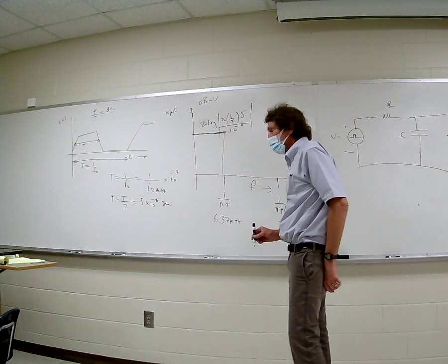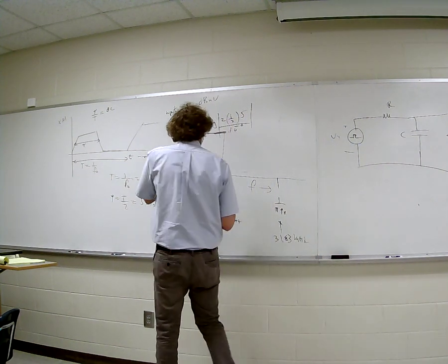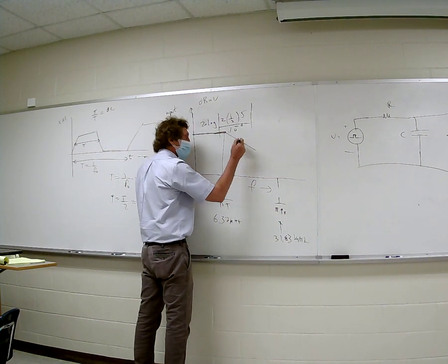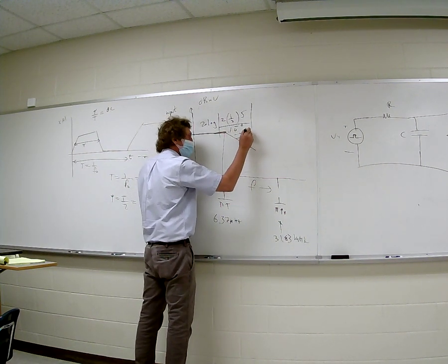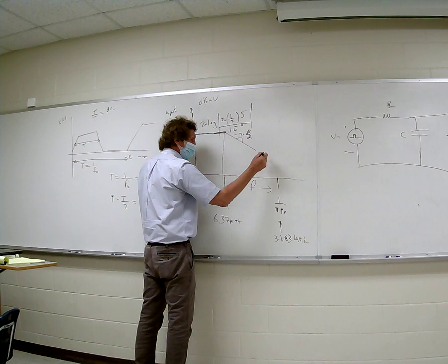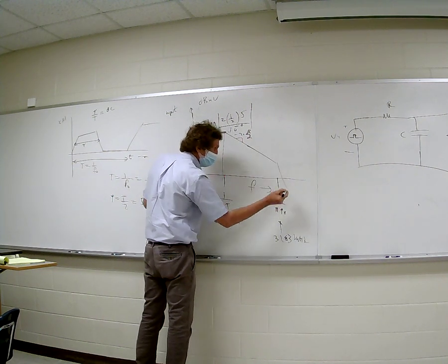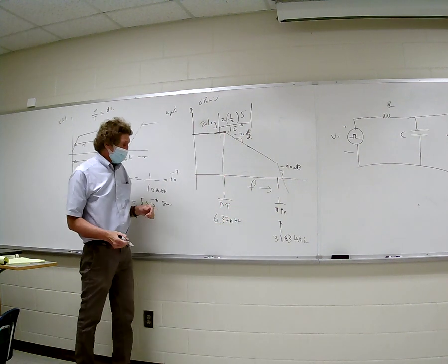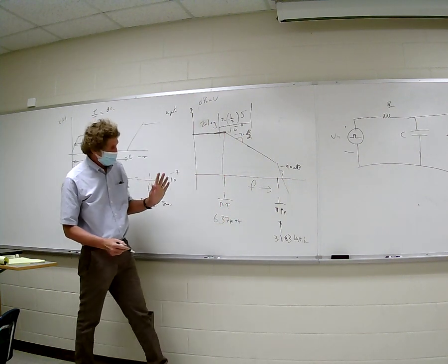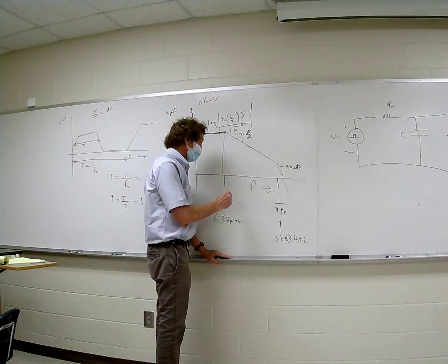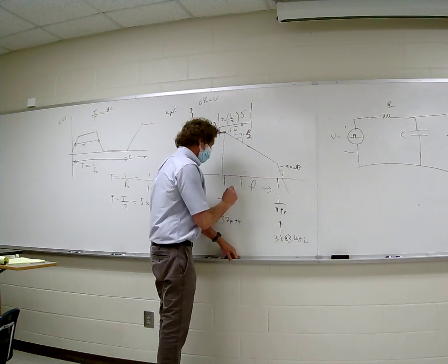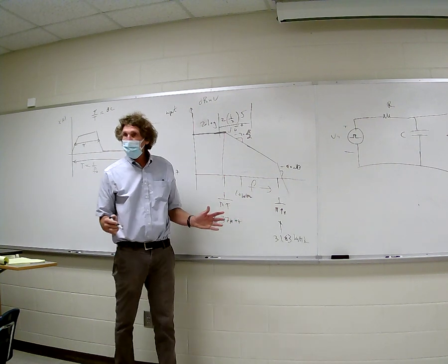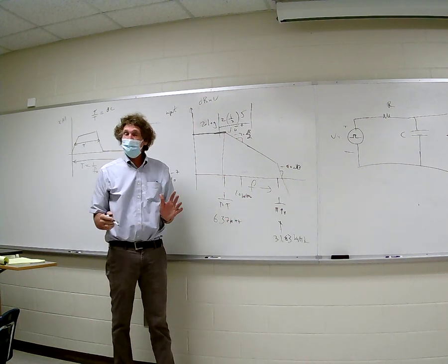You agree? So we start here. We'll get that value in a second. At this frequency, we start going down at minus 20 dB per decade, right? Then we hit this frequency, and then we go down at minus 40. All right, now the fundamental is what? 10 megahertz, right? That's down here. But we wanted the output value of voltage at the 5th harmonic.